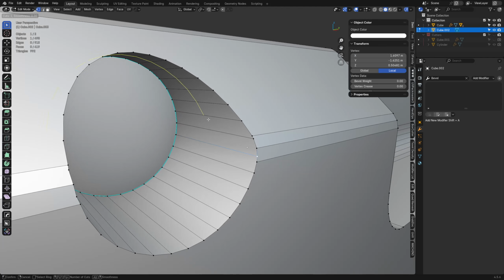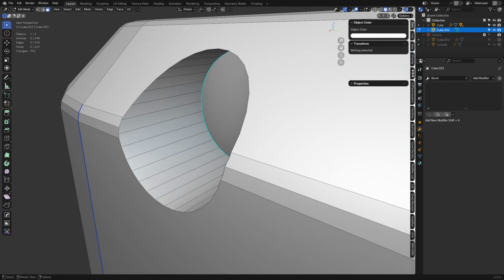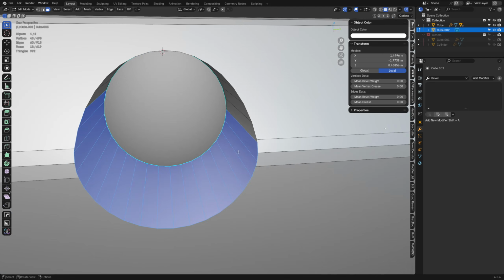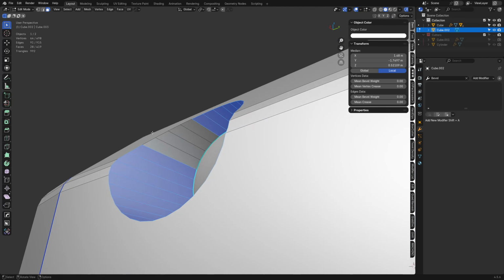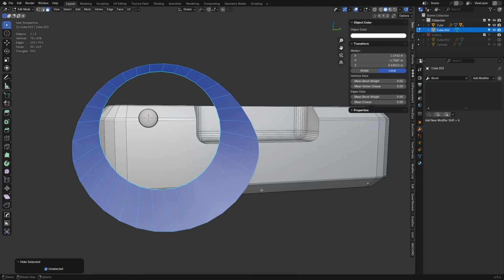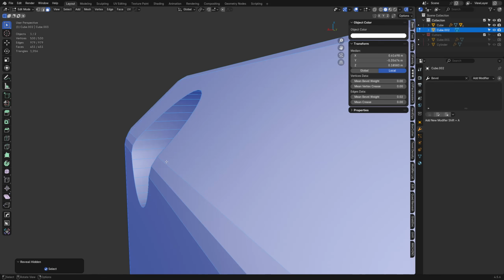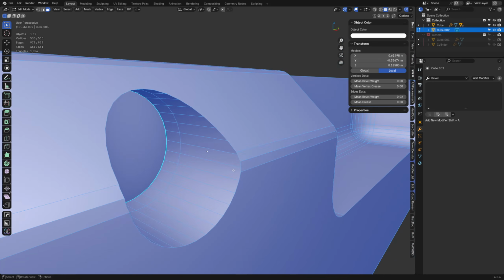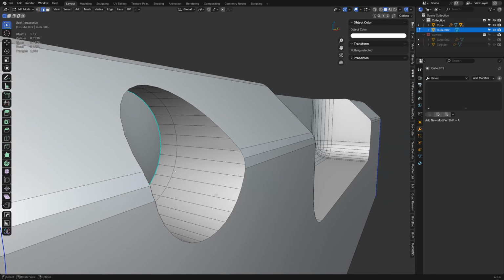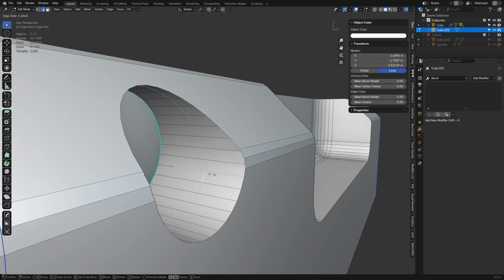Okay, you can see I can't really loop cut through here. It's hard to work with. So I got to use C, use the cursor selector, get in here. And it's not that much fun, right? So Shift H that. I can now get in the side view. KCA. Cut through, space bar, Alt H, bring it back, and we do just cut in there. Okay. If I GG twice this, I can slide it.